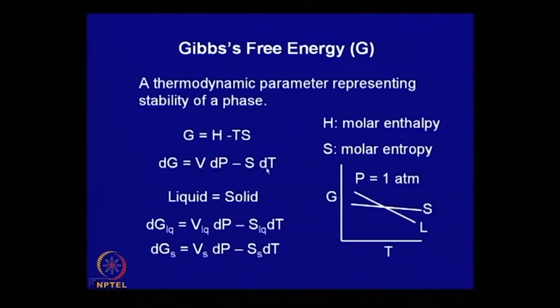minus S dT. Now, let us look at the process of solidification. We are concerned with the relative stability of two phases, one solid and the other liquid. If you try to plot, this line represents the free energy as a function of temperature for the solid, and this line represents the free energy of the liquid as a function of temperature.